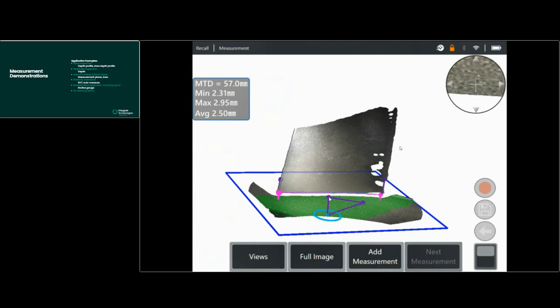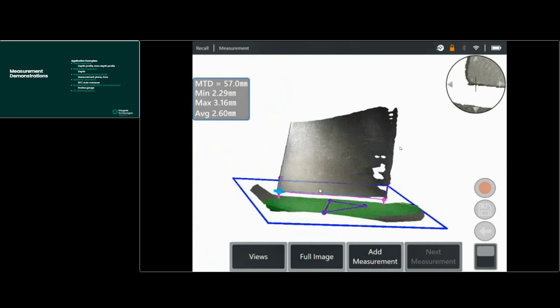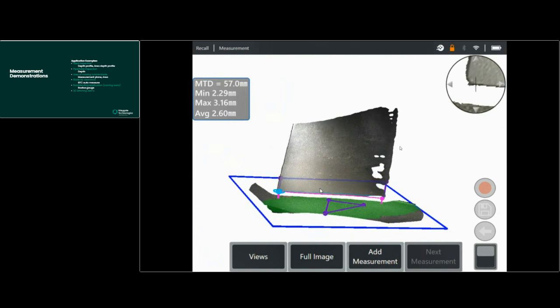You can move the reference plane should you choose to want to, but you cannot adjust these 2 points here. So these correspond to the minimum and maximum points in terms of the greatest and the shortest lengths from the blade tip clearance. These additional points here and here on the trailing edge are the extremities, so the range upon which the measurements are taken.